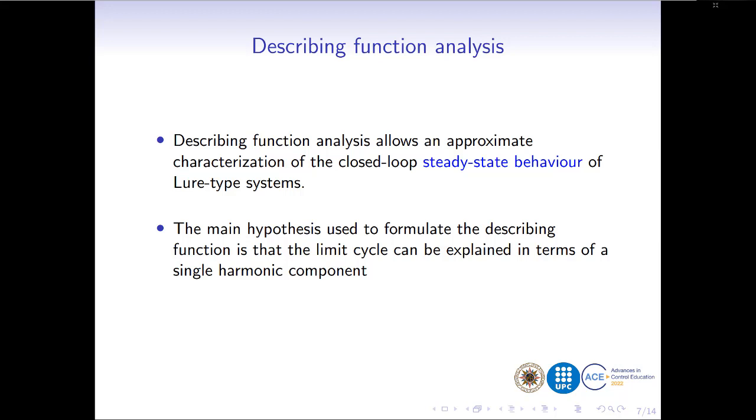Describing function analysis assumes that it works with a Lure-type system and offers a heuristic methodology that allows an approximate characterization of the closed-loop steady-state behavior of Lure-type systems. It is a classical approach already developed and presented in the 1960s by authors such as Atherton or Gibson, but which continues to offer useful and interesting results, especially for engineering students. It is also a technique capable of handling non-linearities that present discontinuities or that are piecewise defined.